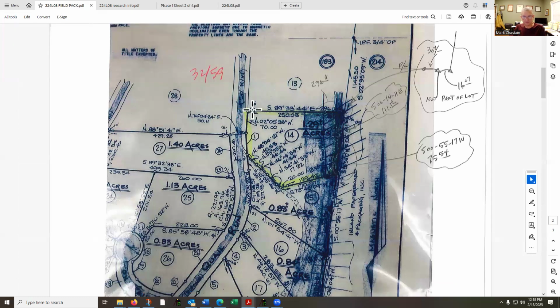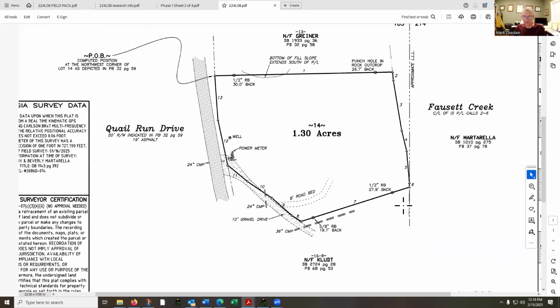Most of these are to the nearest foot. So if we're within 3/10 on something that's calling for the nearest foot, we're certainly within some tolerance there. It would have been just as, and possibly more, defensible to have created this calc point 20.00 out towards this driveway, because 20.00 was the distance on the plat.